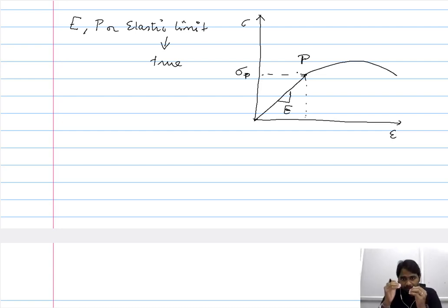Now if you observe a discernible movement of the dislocation, what I mean by discernible movement is when you are doing what you commonly call in situ testing of the material. You tensile test your material within the microscope and you observe what behavioral changes or microscopic changes the material exhibits. When you do the tensile testing within the microscope, if you are able to discern that there is a dislocation movement, then you are beyond the true elastic limit. So this idea of true elastic limit comes from our understanding of dislocation.